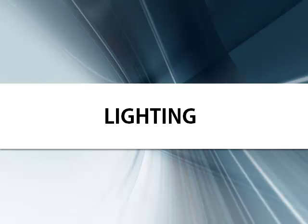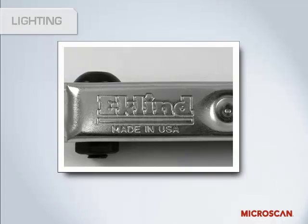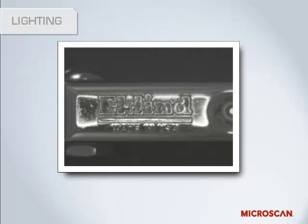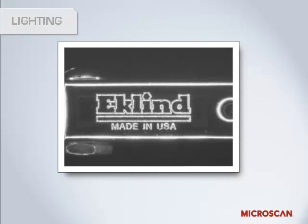Proper lighting is critical to the success of an application. The type and position of a light should be carefully selected to maximize contrast of the features you plan to inspect and minimize contrast of everything else. This is like an electrical engineer setting up a system to give a high signal-to-noise ratio. You're trying to make the pieces you need to see, or need to measure, very clear, and you want all the other items in the image as invisible as possible.